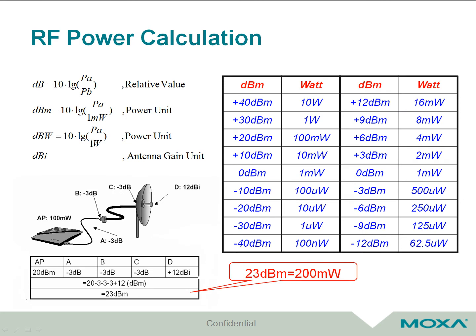Decibel is the unit used to measure signal power, including transmitter power and receiver sensitivity. Decibel is a logarithmic value that expresses ratio between two values. In our case, it is signal power. It can represent signal loss, for example. As you see from the equation here, it is actually a logarithm to base 10 of the ratio between measured power and base power value. If we agree to use a fixed base power value, decibel can represent an absolute value.